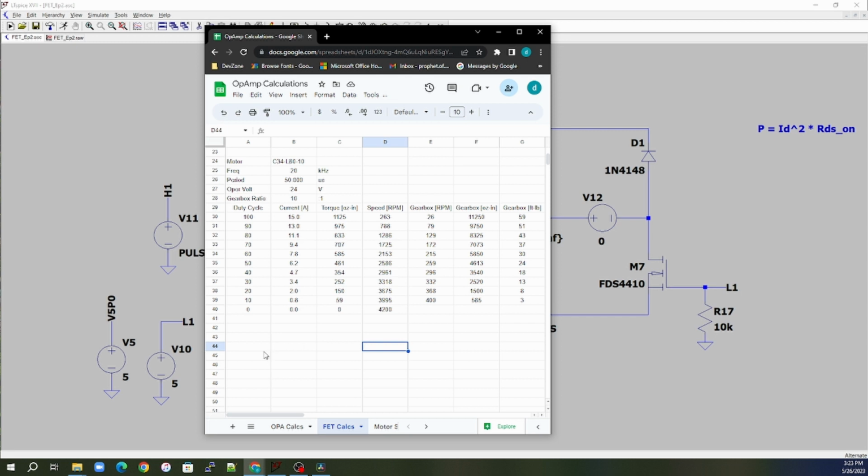So you might want to say, I've got 3 settings on this motor. I want it to run a high torque, a medium torque, and a low torque setting. So what does that ultimately mean with the electronics? Well, if you want to control the torque output, you want to control the current output, because we already know that our current dictates how much torque that we can get out. So then how do you control the current? Well, you use the duty cycle. If we adjust the duty cycle of the motor, then we can adjust the current. If we adjust the current, then we can adjust the torque.